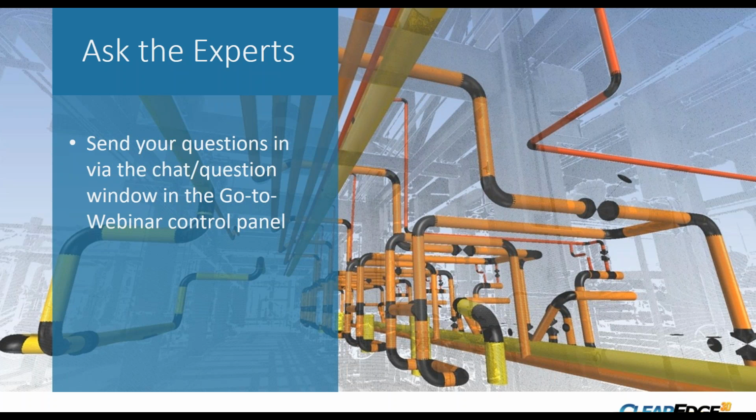I don't know all the lingo that we've got in our laser scan risk management department. I have not digested that entire document, so I really can't. I know that there are perceived tolerances in the laser scans themselves. The one we use is 2 millimeters, so as you're registering everything together, there's that inherent error. They just need to know that, based on data in the field, as long as everything's registered together right, it's more accurate than you're going to get with a tape measure a lot of times.